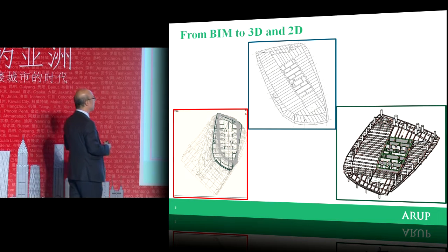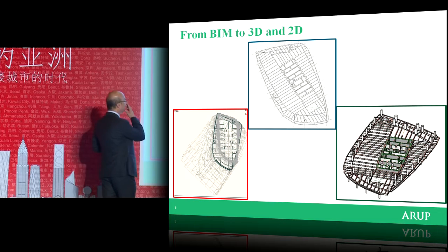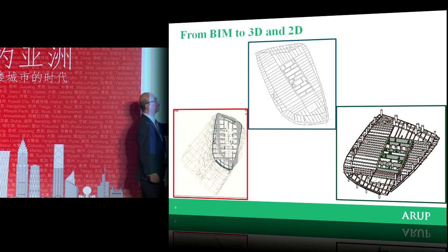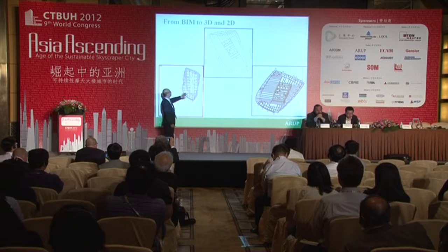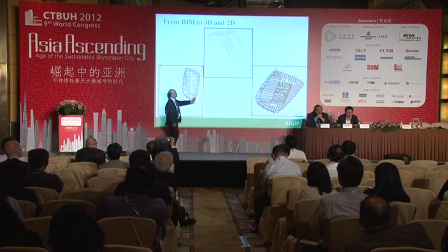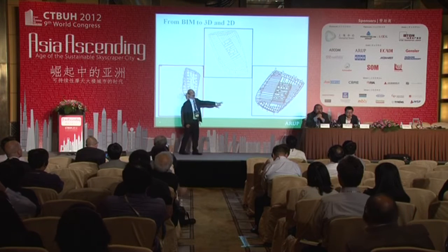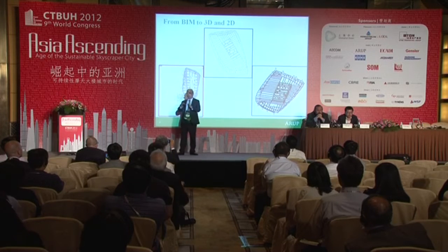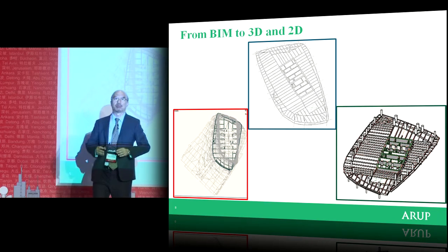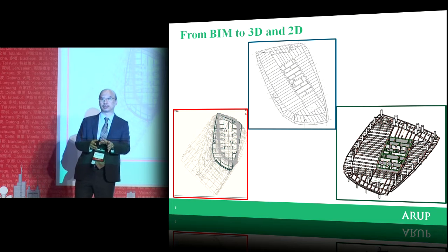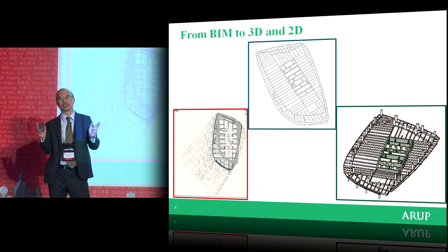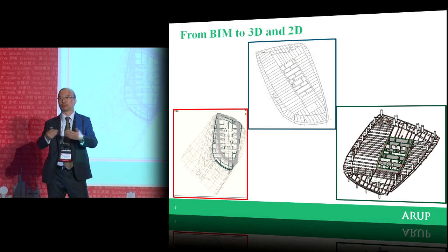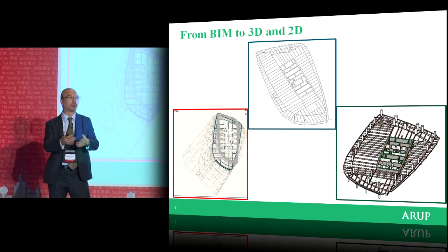Now, this one shows the structural analysis model in 3 dimensions. We show it on the plan, and this is the BIM model, and this is the CAD drawing. Now, the process is we get the BIM model, but we still need to convert it into a standard 2D CAD drawing so that the contractor or everyone can work on the 2D, right, at that time.